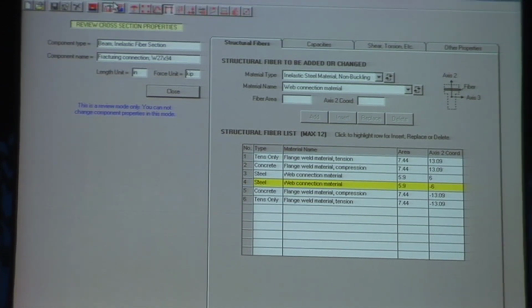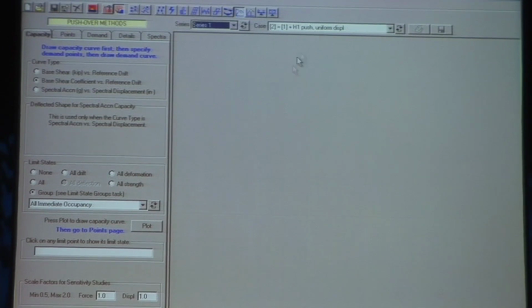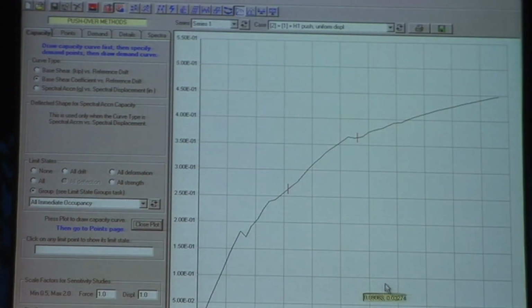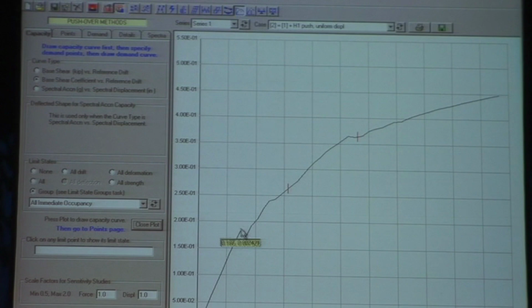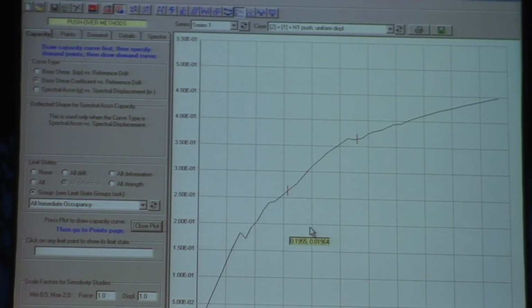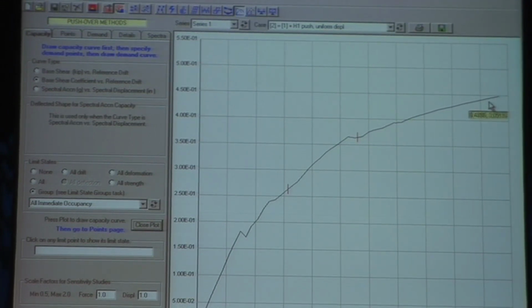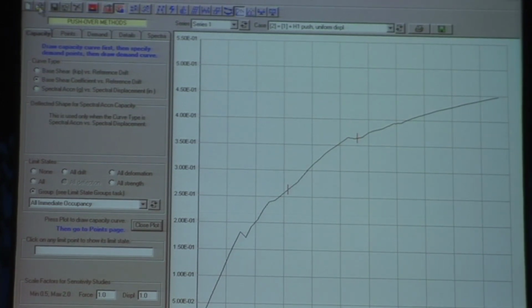And then I've run analyses, and I've run a pushover analysis in the H1 direction, and I'm going to plot the pushover curve. And there's some jiggles here. These jiggles occur where the connections fail. And without going into details, I can tell you by the time it gets out to the end there, every one of those connections has failed in tension. And remember this number, it's 0.45 G. There's a strength out here, about 5% drift. Okay, then I'm going to go to a second model.